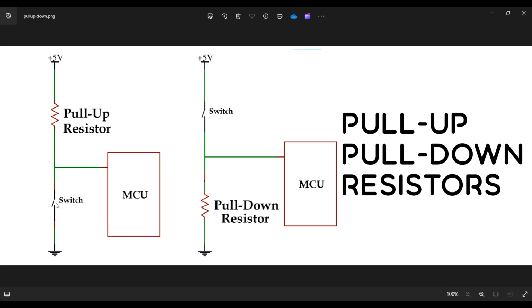So when the switch is disconnected, it is connected to VCC. However, the path to VCC is weak because of the high resistance, but it is connected to a high value, and it is not disconnected from everywhere and does not pick up noise. Or, as I said, the high Z situation does not happen.